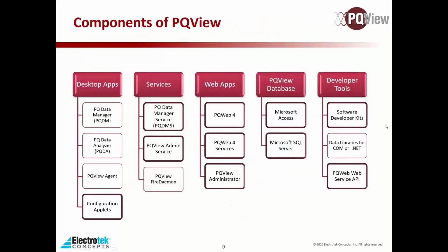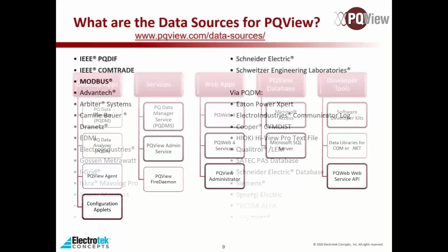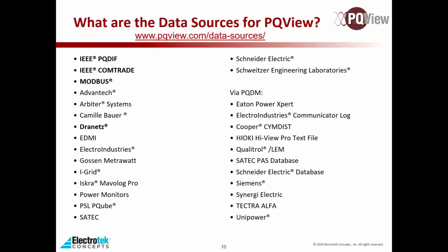And then we'll go into this a bit more in detail a little bit later, but we also have developer tools, as I mentioned before, for our extensibility. So the data sources for PQView, as we mentioned before, we're trying to be device and standard agnostic. Right on the top here, we do support IEEE PQDIF and ComTrade. We also support Modbus for getting data in. We do have custom data handlers for systems, and that's what these are here.